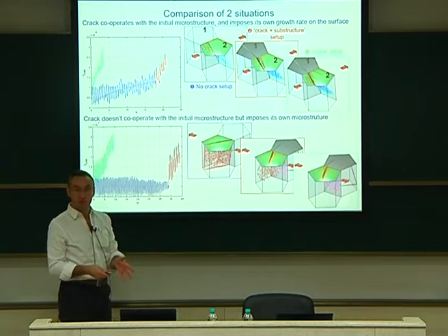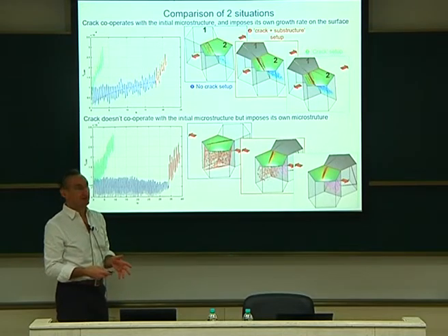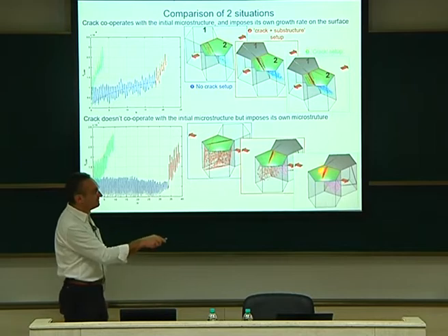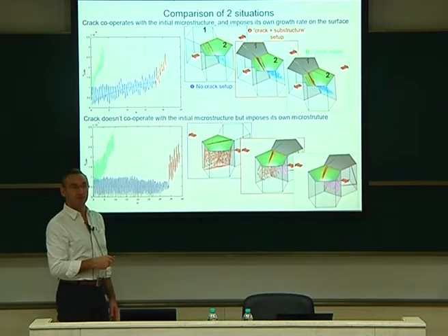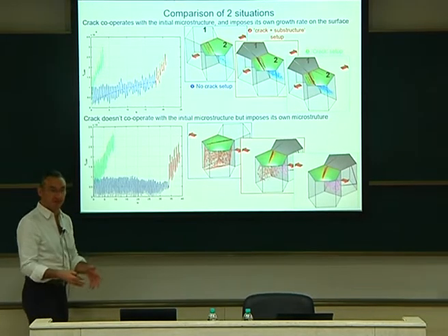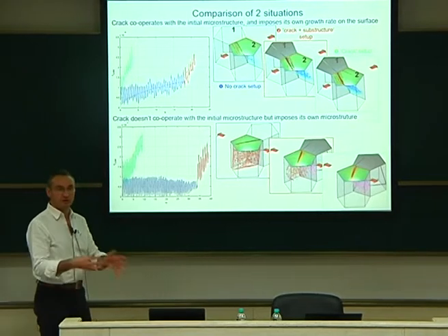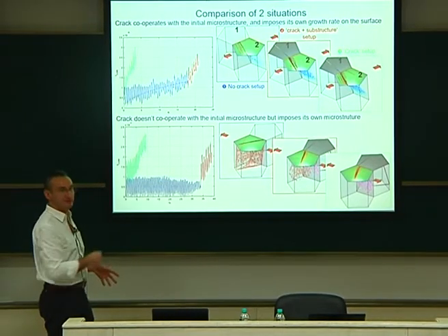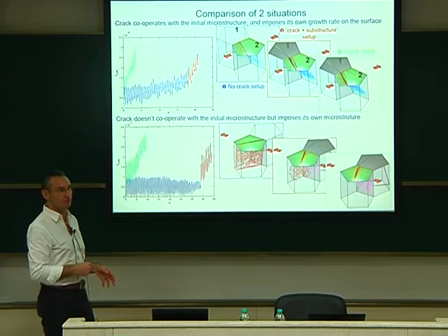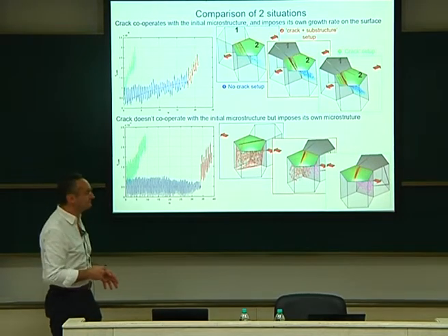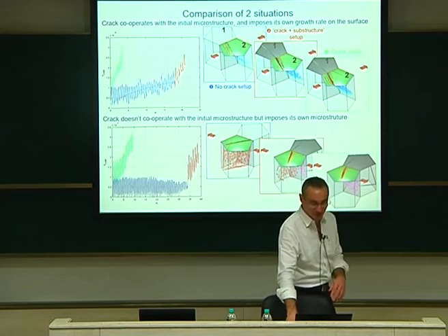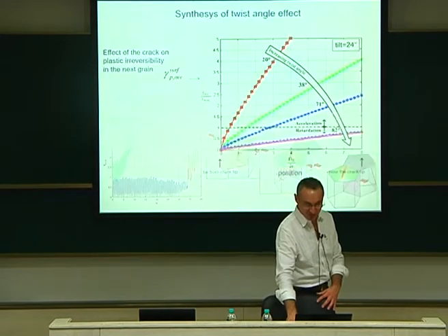So the crack has a huge power on fatigue. You see, if you didn't have the crack, you would get this. Because of the crack, you get that. This is very important. So you can see that the crack stress field totally modifies locally the stress state in your grain. And the persistent slip band forms in other places than expected. Okay, that's the main conclusion on that. I hope I didn't lose you. I think it's quite complicated now. That's the latest result we did on that.